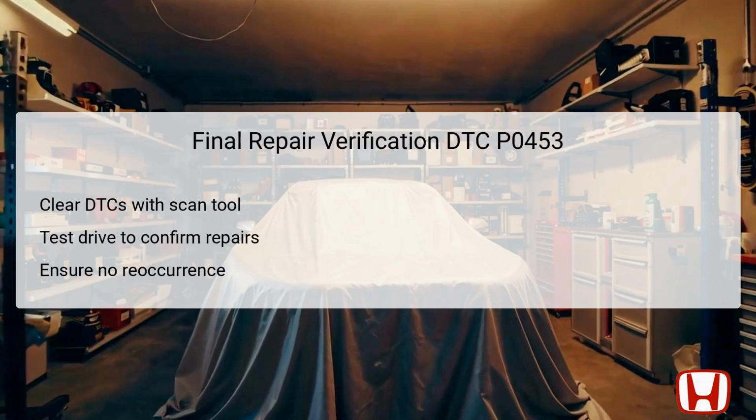After necessary repairs are made in response to DTC P0453, it's vital to verify that everything is functioning properly. This is accomplished by clearing the diagnostic trouble codes using a scan tool. Once the codes are cleared, a test drive should be performed to ensure that the FTP sensor operates normally under various conditions. During the test drive, it is essential to monitor the FTP sensor readings through the HDS to confirm that the repair holds and that the MIL does not illuminate again. Successful verification of repairs involves confirming that the FTP sensor voltage readings remain within specification and that no further DTC related to the FTP system occurs. This step guarantees that the issues have been completely resolved and vehicle performance and compliance with emissions are maintained.